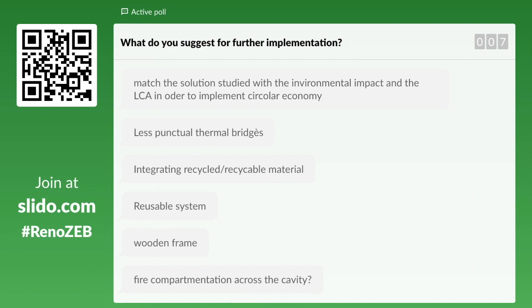About thermal bridge, we have a profile with a polyamide profile in aluminum, so we reduce the thermal bridge, and we have no particular problem from this point of view. Obviously, aluminum does not have great thermal performance, but it's quite a consolidated technology to be used with polyamide to reduce thermal bridge.